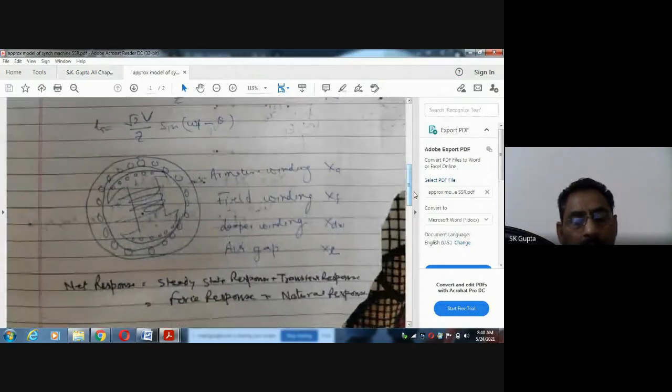Yes. Now, just see this. Earlier also we described this figure. It is showing figure 4, a synchronous machine, where this is the stator winding, this is the field winding, and here in the rotor there is a damper winding. Here in the rotor there is a damping winding, and they are short circuited. Short circuited means this is say the front end and the back end is here, so they are short circuited from front to back. So this is the damper winding, and here it is represented like this.